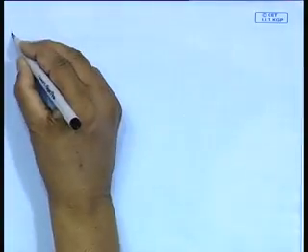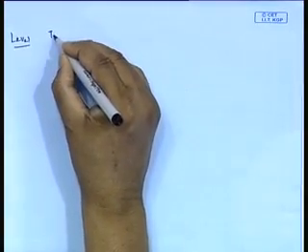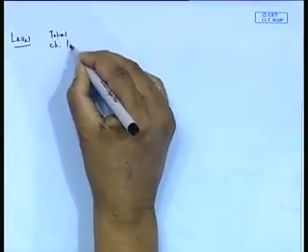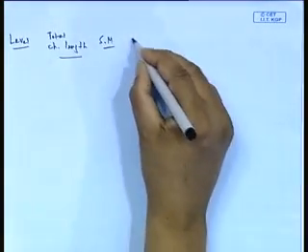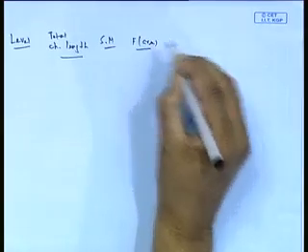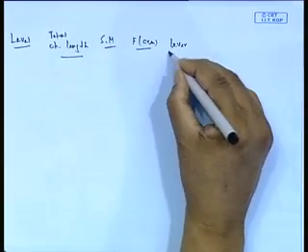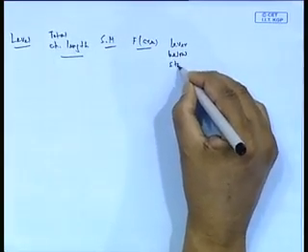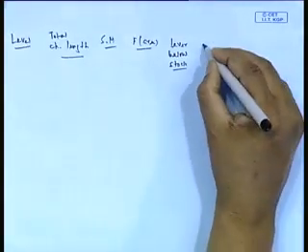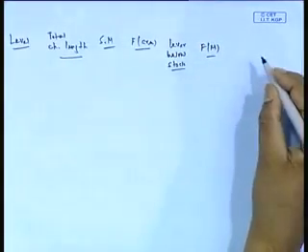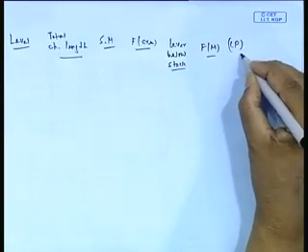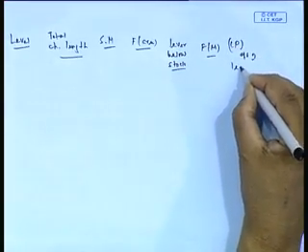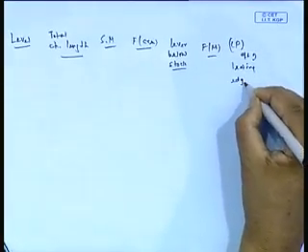So, you have things like this, let's quickly do chord length, then Simpson's multiplier, then F function of area, then lever, this is to find M, then function of moment, then Cp aft of leading edge.